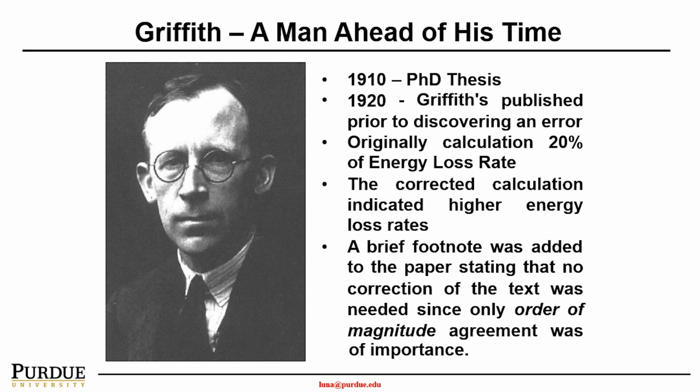He was really inspired by why the theoretical stress of the atomic bond of a glass is about 10,000 megapascal, whereas the stress needed to break a bulk glass is only about 100 megapascal. So he studied this and published the paper. An interesting part is that in a brief note added to the paper, he stated that no correction to the paper was needed, since only order of magnitude agreement was of importance.